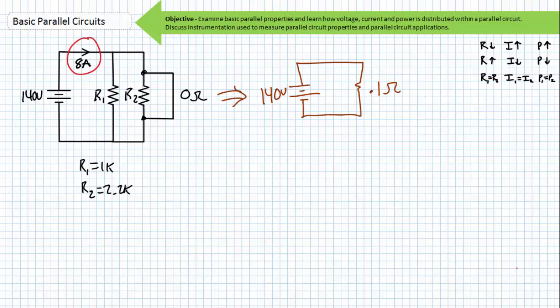In this case, the current would still theoretically spike to an astronomically high value, where 140 volts opposed by 0.1 ohms of resistance would yield a current draw of 1,400 amps. However, the circuit breaker, experiencing a current draw in excess of 8 amps, is going to shut her down by opening the whole circuit.